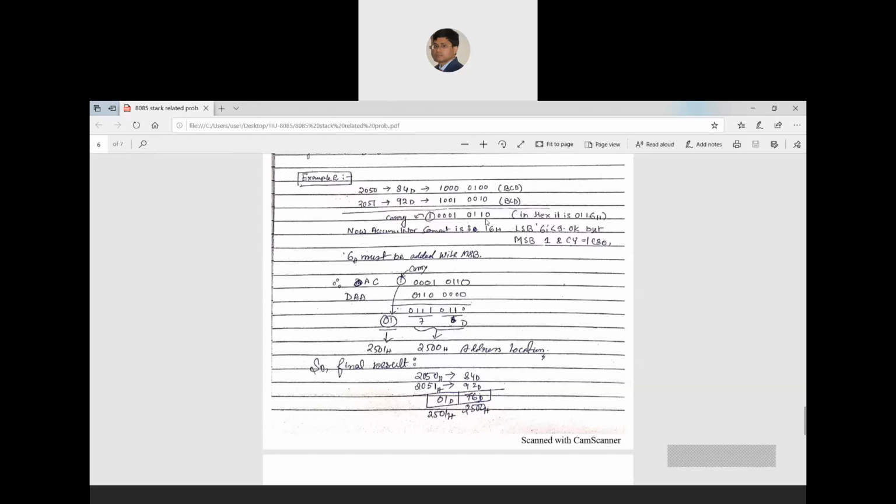So I have already discussed two examples. The first example is where the microprocessor checks the MSB and LSB digits, and the result is not in the range of A to F. That is a very straightforward and simple example where the microprocessor just sees the result, and both digits are not in the range of A to F. That means the microprocessor has to add 66, both the digits 6 and 6, right?